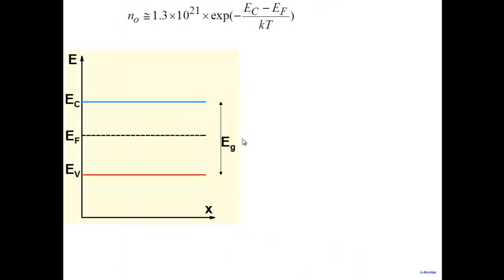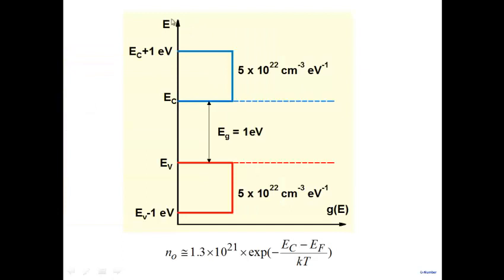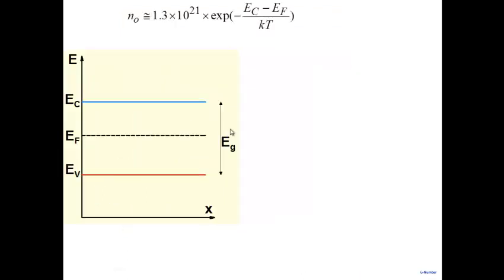So in any semiconductor, now it's a simplified representation. Note that the previous diagram was E here and density of states here, and we were showing the density here and all that. Now I'm showing an energy band diagram where we have electron energy as a function of x here. x is within the semiconductor. We have EC, so we are denoting only the bottom of the conduction band. Of course, the band extends from this one here, and there are energy states above it. Similarly, EV is here. We are denoting the top of the valence band here.